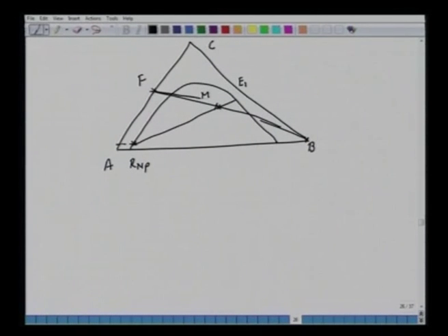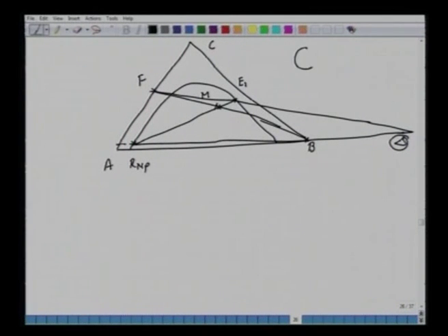We connect this to obtain E1, last stage. And now we are connecting with this to obtain our difference points. So you have to extend this till we locate this delta. Okay, now I start from here. First stage, 2 leaving streams, E1 and R1 in equilibrium. Take this line, now you draw a tie line. So we have this R1. Connect this R1 with the delta point.